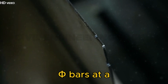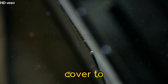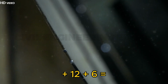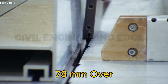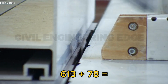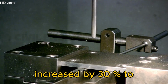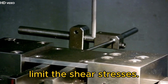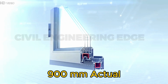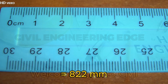Provide bars at a clear cover of 60 millimeters. Effective cover to upper layer of bars equals 60 plus 12 plus 6, equals 78 millimeters. Overall depth required equals 613 plus 78 equals 691. The depth may be increased by 30% to limit the shear stresses. Provide an overall depth of 900 millimeters. Actual effective depth d equals 900 minus 78 equals 822 millimeters.